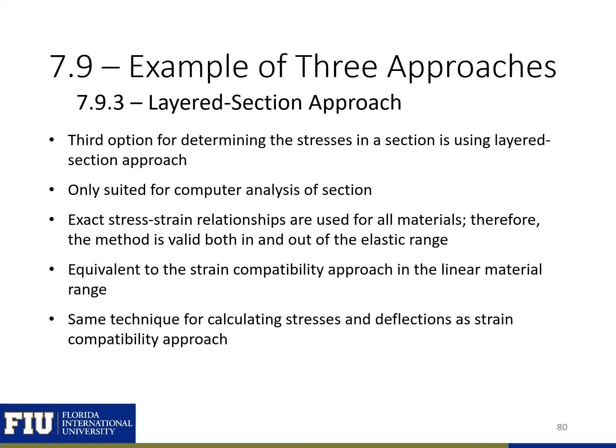Our third option for calculating stresses is going to be using a layered section approach. This approach is much more complex. It's an approach that uses exact stress-strain relationships for all of our materials, so it's valid both in and out of the elastic range. And it's about equivalent to the strain compatibility approach if we're in the linear elastic range.